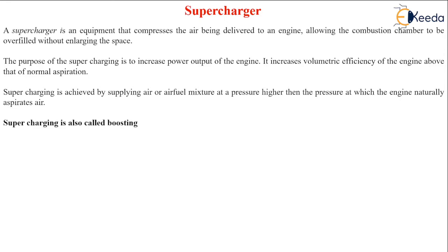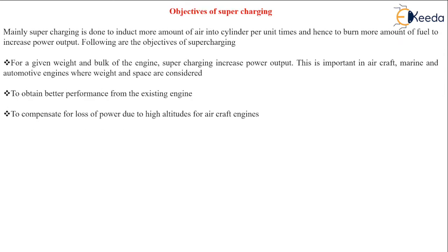Now, let us go on a bit further. What are the basic objectives? We say that supercharging is done, as we already discussed, to induct more amount of air by compressing it into the same space of the combustion chamber. If more amount of air is inducted, more amount of fuel will be burnt, and if more amount of fuel is burnt, this will in turn lead to a larger power output.